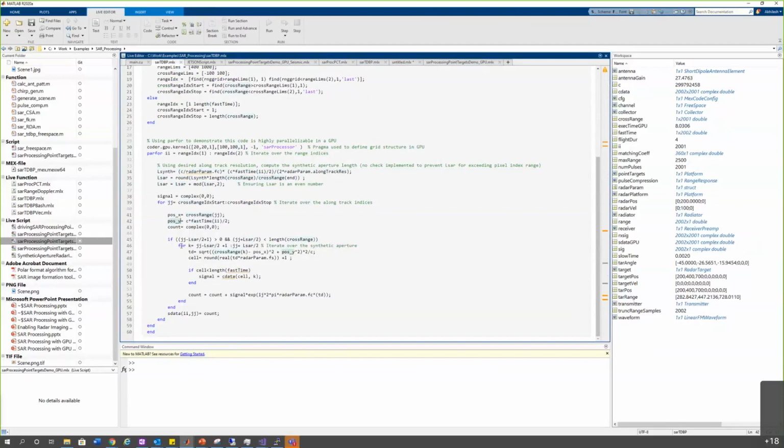And then there's another third for loop, where we're synthesizing the synthetic aperture. Again, we don't have to go into the details of what's going on, but really for every pixel point, we do a backtracking as if to find where the ray is coming from. We compute some time difference, a time delay, and then we apply the phase compensation based on that time delay. So, exponential 1j 2 pi, the center frequency times the signal, and then we start adding those pixels, superimposing those rays one over the other over the other.